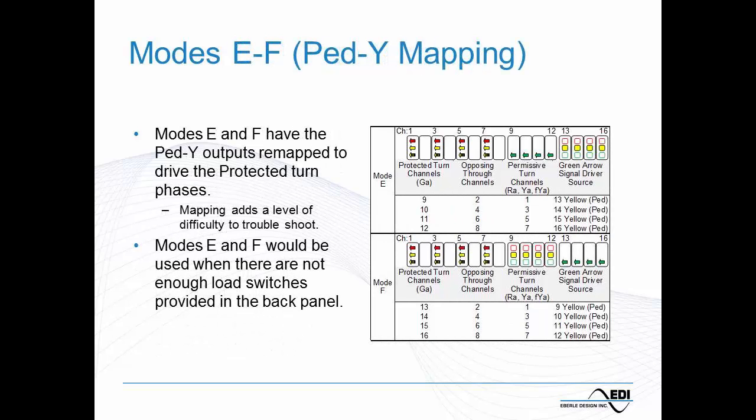Now, we mentioned the possibility, well, maybe we have a 12 position back panel, maybe we have some other overlaps we need to use. We have modes E and F. In this case, the monitor is going to assume that we're going to remap the function of the Ped yellow output. Let me just start off by saying in most cabinets, that Ped yellow output, well, it certainly doesn't drive